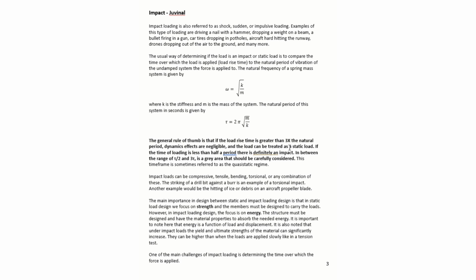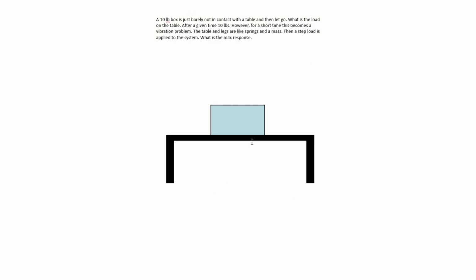However, if the timing of the load is less than half a period, there is going to be an impact. So the example back here with our block coming in contact with the table, that ramp up is nearly instant. And that's why this would be an impact load.